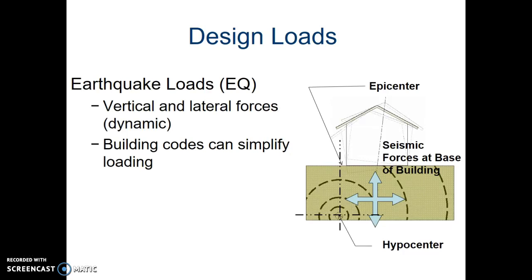The earthquake or seismic loads are based on the location of the structure, the type of soil on the building site, the type of construction, and the building's mass. Also, the shape of the building has a lot to do in earthquake load designing. Seismic maps depict the potential risks for earthquakes in various areas, and building codes will simply include loading conditions for structures.